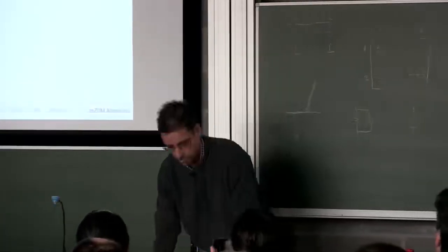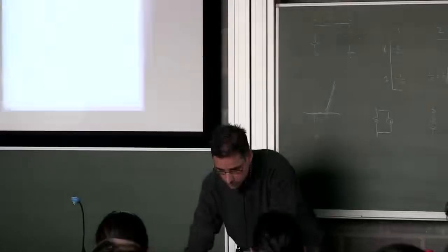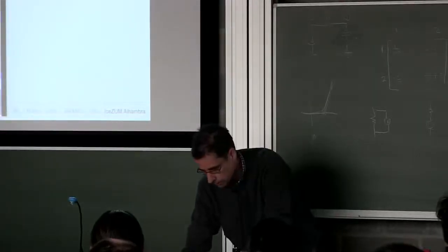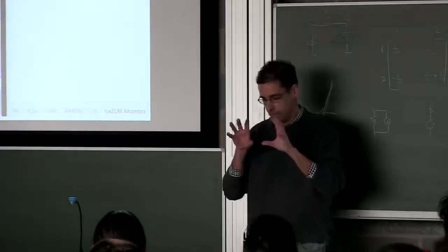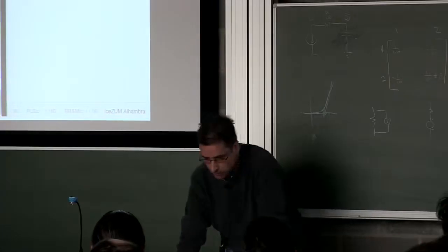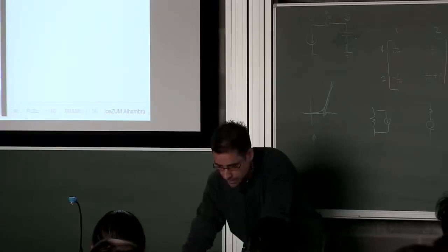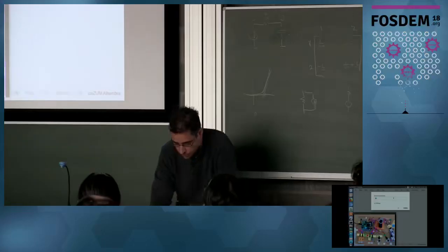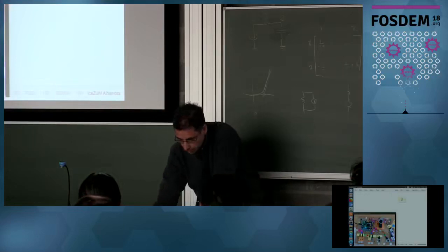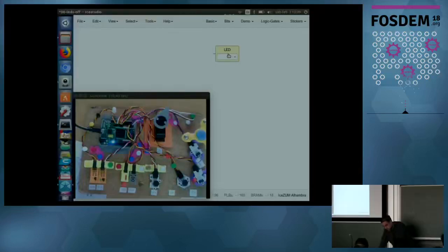What I have here in the background is Icestudio, this white background. In that background, we are inside the FPGA. So the first thing we are going to do is place an output pin. We are inside the FPGA, we want to go outside, so let's call it LED. This is an FPGA pin, and for turning on an LED, we need to put a 1.